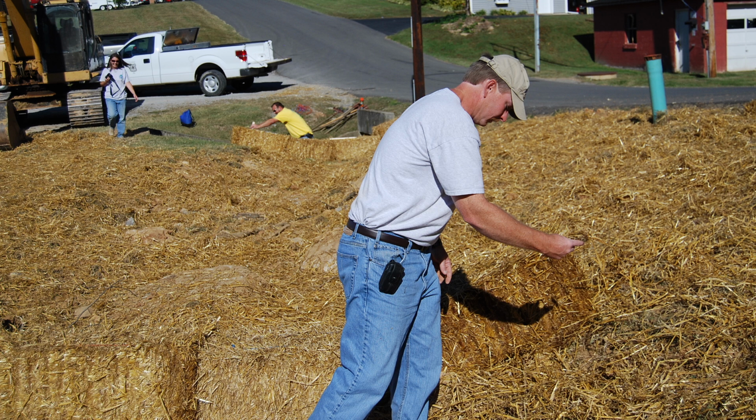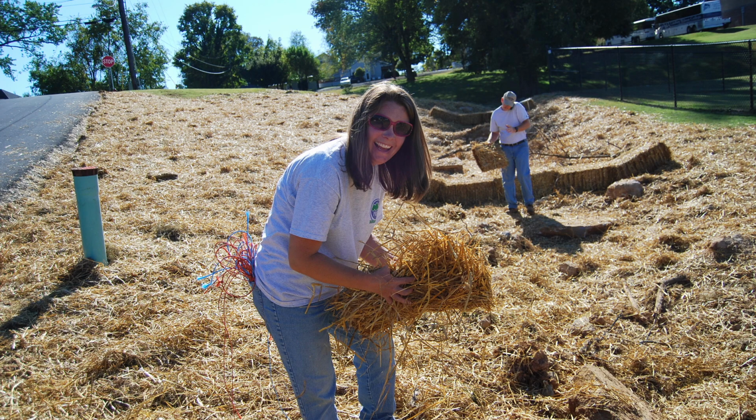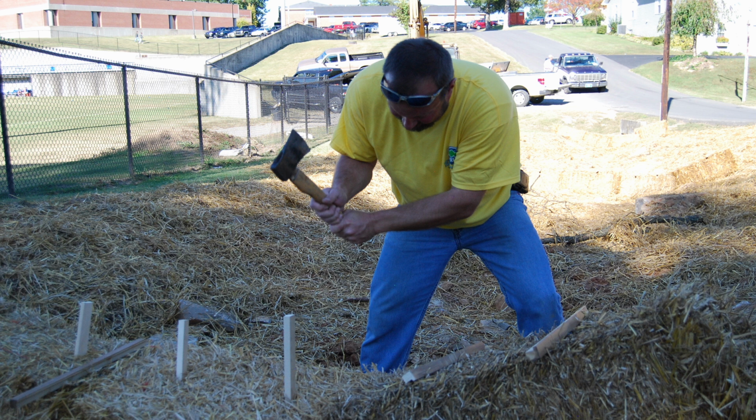We sowed the exposed soil with wheat and mulched using straw to control erosion and to promote the germination and growth of plants. Covering the ground with straw also helped to gain acceptance for the project by removing the shock of seeing so much exposed soil. We anchored straw bales across the floodplain just in case there were heavy rains with significant runoff before the plants and the roots could get established to prevent erosion.